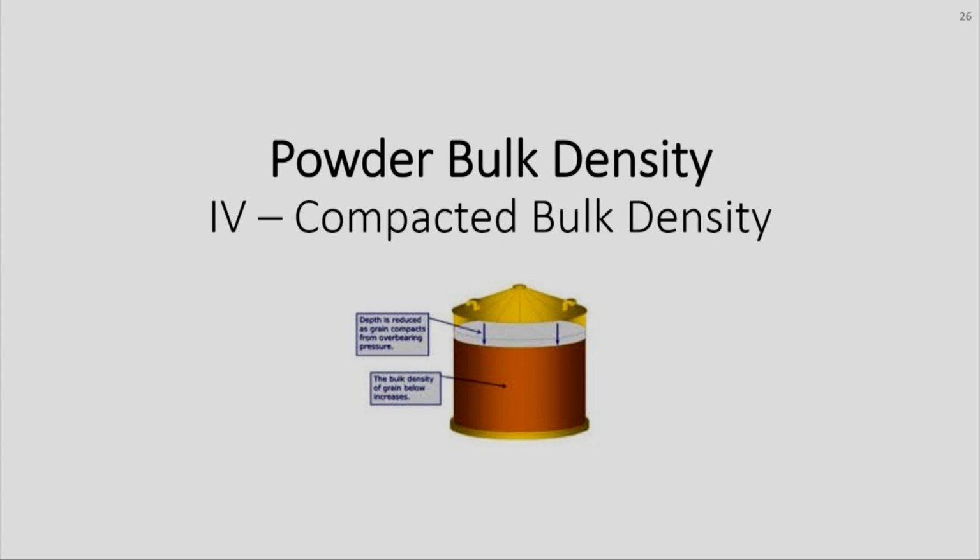So that's again one common place, at least in food and grain, where we use it to get the actual amount of material, due to this change in density. Okay. Same thing for shipping too. For inventory calculations, how much material you have in the bin, you'll have to use the compacted bulk density.